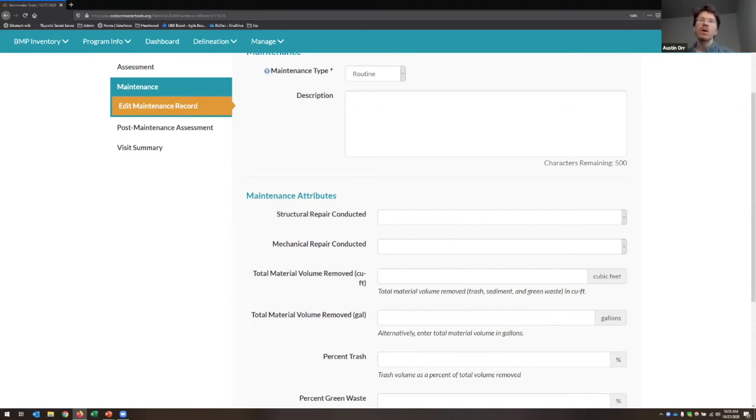Yeah, sure. So our treatment rate nomographs are designed in particular for volume-based BMPs, and they're calculated using long-term continuous simulation. So we actually do a long-term continuous sizing calculation for a wide range of BMP volumes and expected drawdown times.